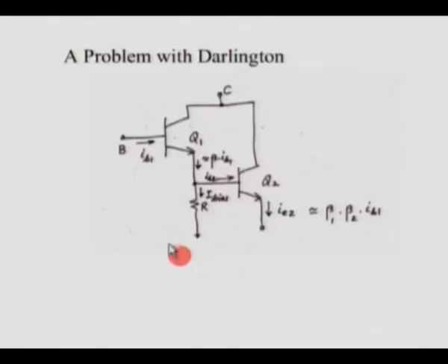Now, the solution is to introduce a resistor after the first stage and connect it appropriately. In an IC kind of amplifier, it will be best to put a current source here, but in a discrete amplifier it may be difficult to have a current source. So, we could put a resistor here. Now, this resistor needs to be chosen very carefully.